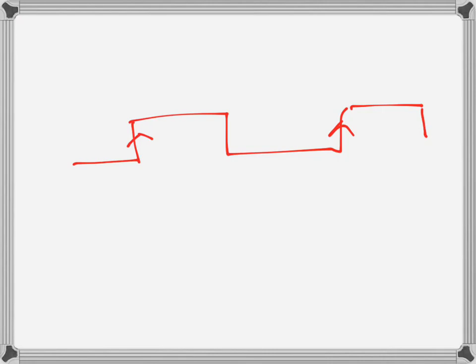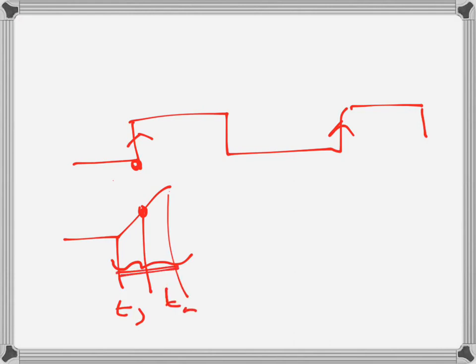So the flip-flop takes a while, before the clock comes and after the clock comes, in order to accept its input. Instead of being right at that point, or right at the middle point, there is a range of time. Before that is setup time and after that is hold time. During that time the input cannot change, it has to be a certain value.